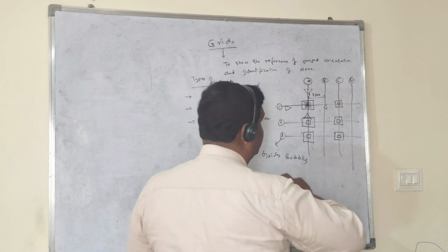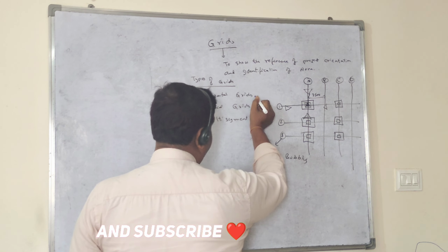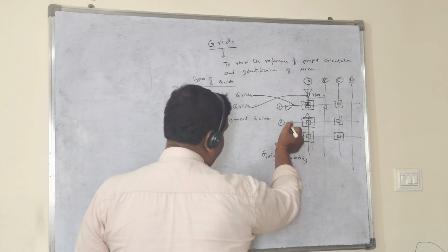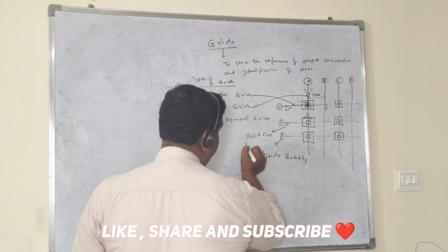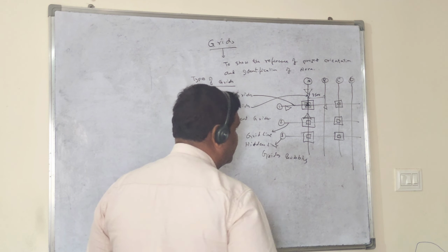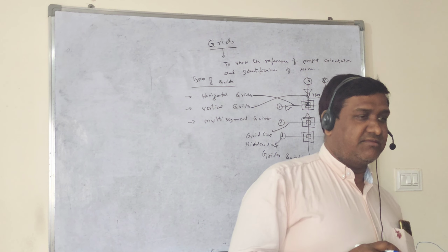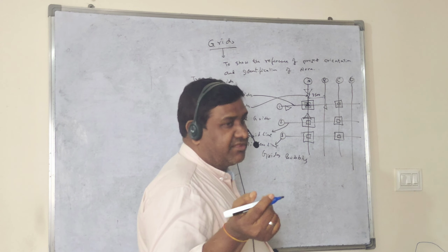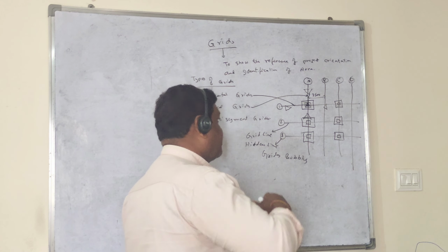So this is horizontal and this is vertical. Whatever lines you are finding, these are grid lines, and the grid line will be a hidden line, because grid lines are always identified with the help of hidden lines. Dot dot dot dot, it will become hidden lines. I just drew a solid line here, but when you do it in Revit projects, it will become hidden lines. Okay, so like that the grid will be identified here.